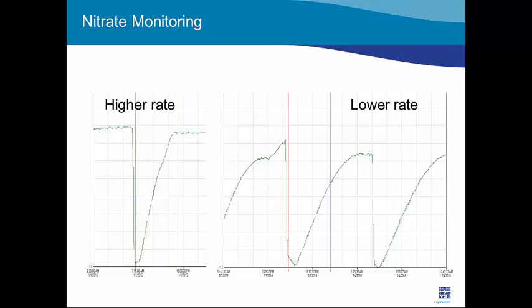One action they could take: if they found that their rate of nitrate generation, or in other words their rate of nitrification, meaning their nitrifying bacteria are in poor health or need a boost, they could choose to increase the DO concentration in their main reactor tank. This way they know they're always operating at the lowest possible dissolved oxygen concentration, and they're keeping their nitrifiers alive.